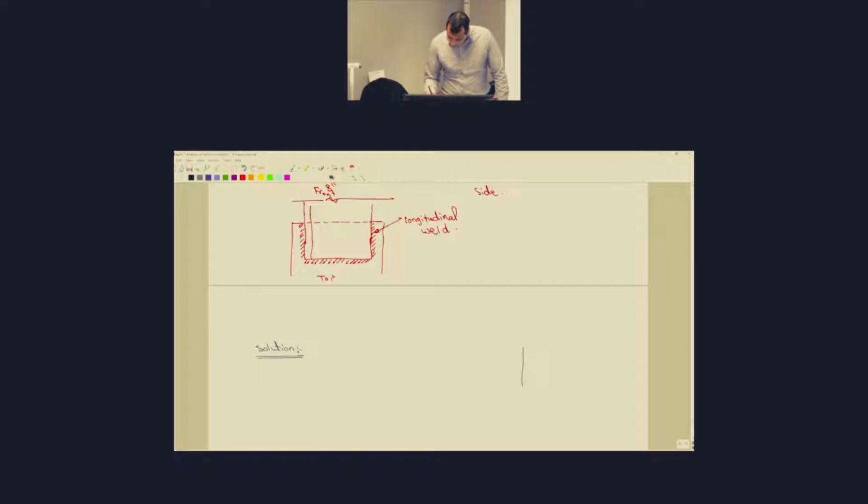So this is your angle. That's the 6-inch leg. That's the 8-inch leg. For calculating the shear lag factor, you're going to need this distance, X bar, or Y bar, we're going to see which distance on the table is going to be called. But in the cases for the shear lag factor, it's always called X bar.